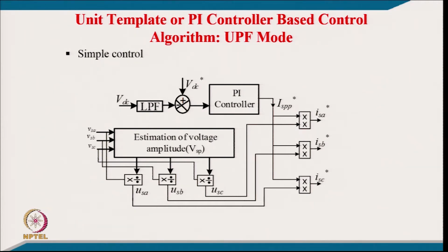Now, sensing the supply voltage here, I mean these three supply voltages, we might be sensing not the phase voltage but the line voltage, and from the line voltage we have to estimate the phase voltage. That relation we would also like to give there. Moreover, these voltages may also be distorted or unbalanced. Sometimes we have to handle that, but we will talk about it a little later. At the moment we will not talk about it.